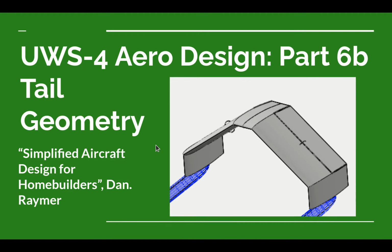And one of those was to help reduce drag on this airplane because I want to be able to fly to some local airports that are fairly far away. So I want to get some good range out of this airplane. And so one of the ways of doing that is reduce the drag. So I want to keep the tail out of the slipstream of the prop on the airplane. So we talked about some of the considerations we're going to give to try to do that.